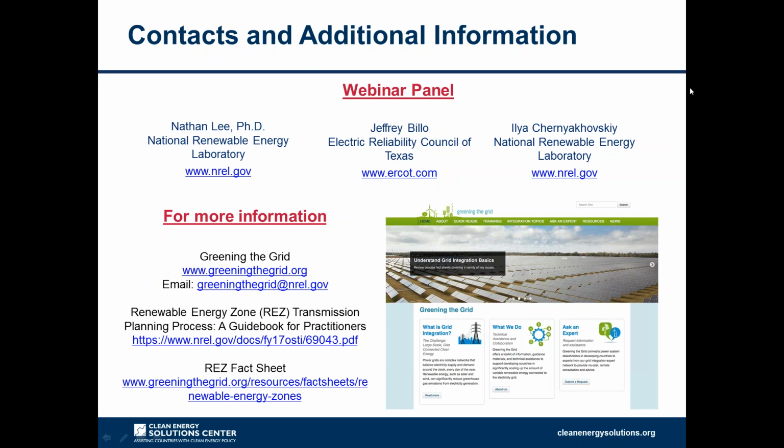No, I think it could work for solar as well. I think the only difference, the different approach I would take for solar, is with the wind generation, we assumed that you could have that 2% annual curtailment, and that was going to be fine. I'm not sure that that would work for solar because solar generation tends to be, when it's on, it's generating at 100% output most of the time. Whereas wind is rarely generating at 100% output. So I think that would probably be the only difference, is you may come up with a little different criteria when you're looking at what is economically optimal. But I think that the process overall would work for solar.